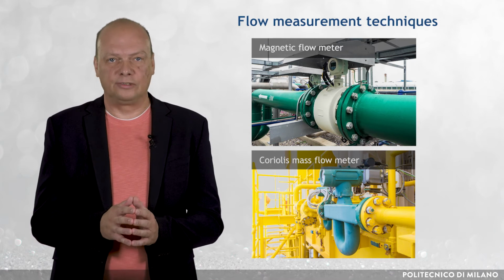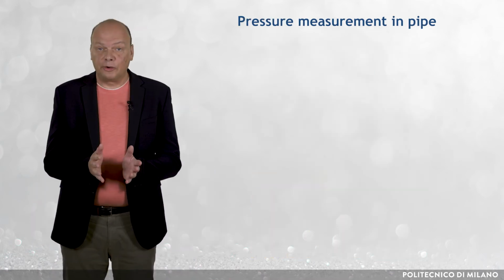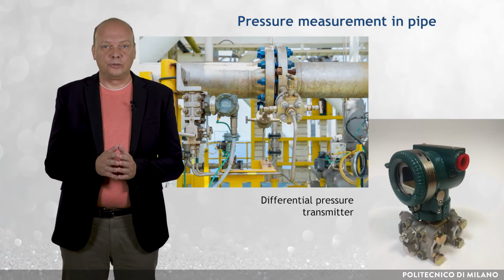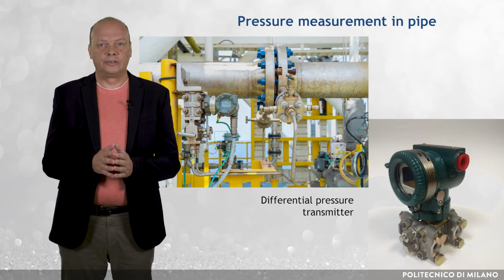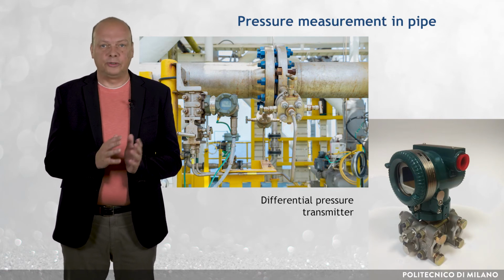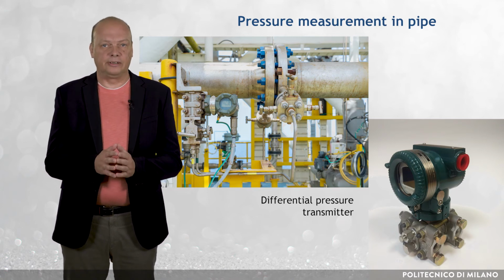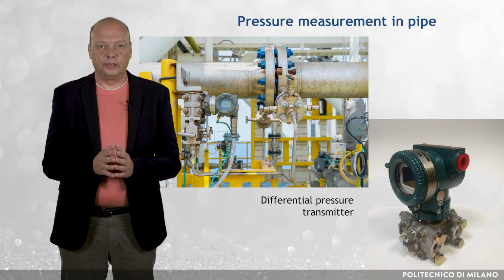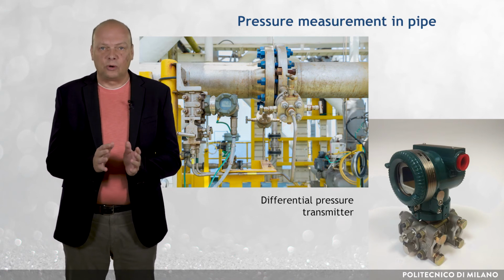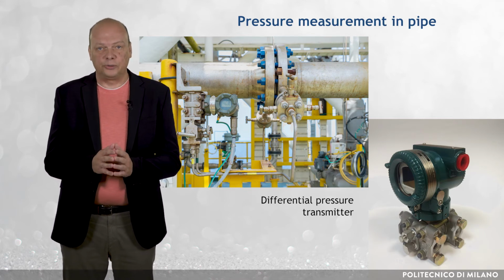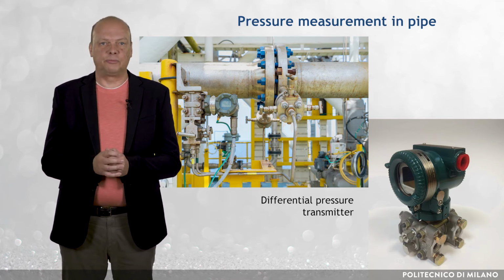For laboratory pressure measurements, the best accuracy is usually obtained by using differential pressure transmitters connected with the pipe through tapping lines and settling pots, which prevent blockage of the tappings and protect the transmitters. The differential pressure transmitters are sufficiently accurate to measure the relatively small frictional pressure gradient while being insensitive to fluctuations in the overall static pressure.